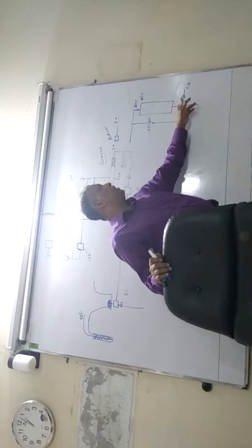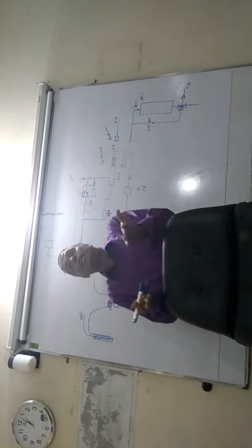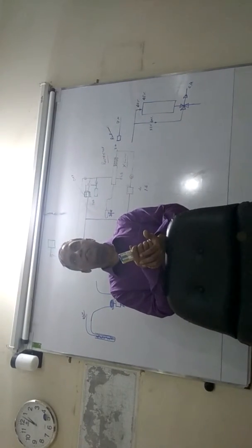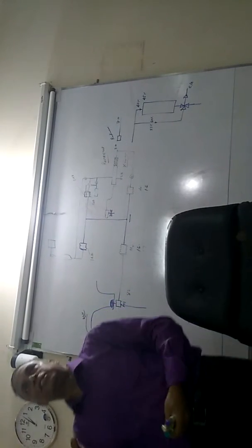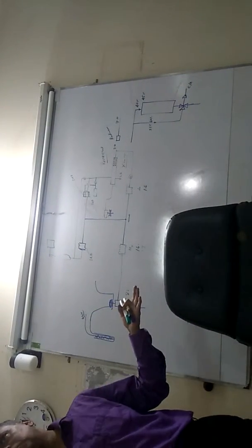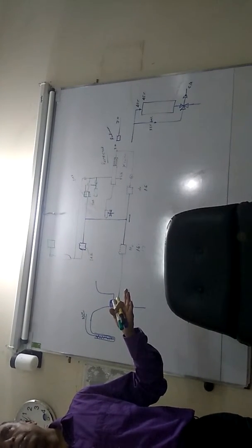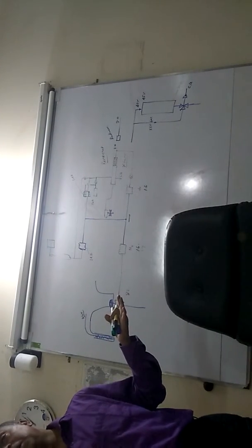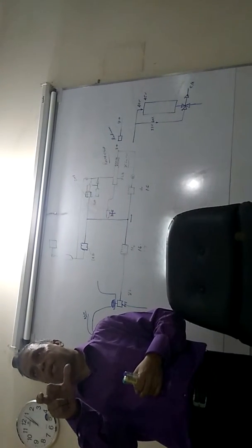So this will bypass even more water, so that will be heating up the water faster. Yes? So that is proportional. It depends on the temperature differentials from the desired value. The higher it is, the more the difference, it can be negative and it can be positive. The higher the difference, the more is the effect on the three-way valve. Yes?